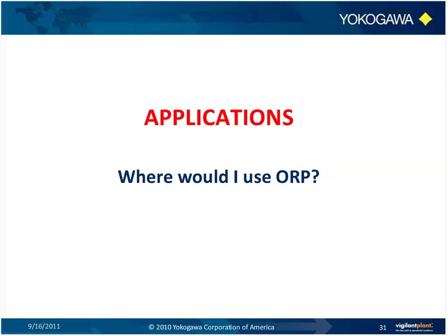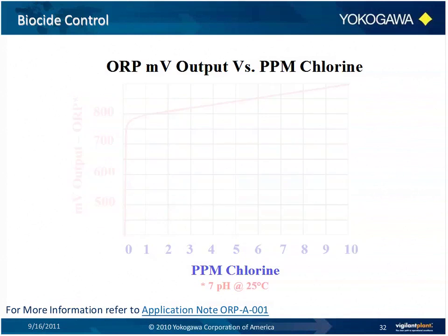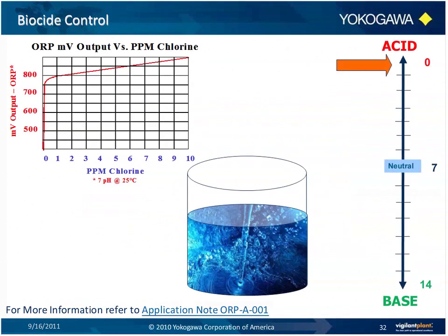But for many years, ORP measurements have caused their fair share of frustration because people didn't know the ins and outs, not like pH. But if ORP is applied correctly, it will provide the accurate, critical information that is needed. ORP can be used to monitor and control many industrial aqueous systems, correlating the millivolt readings to the sanitation strength of the chlorine present in the water. Various chemicals are commonly used to control slime and microbes, but the most commonly used chemical is chlorine.